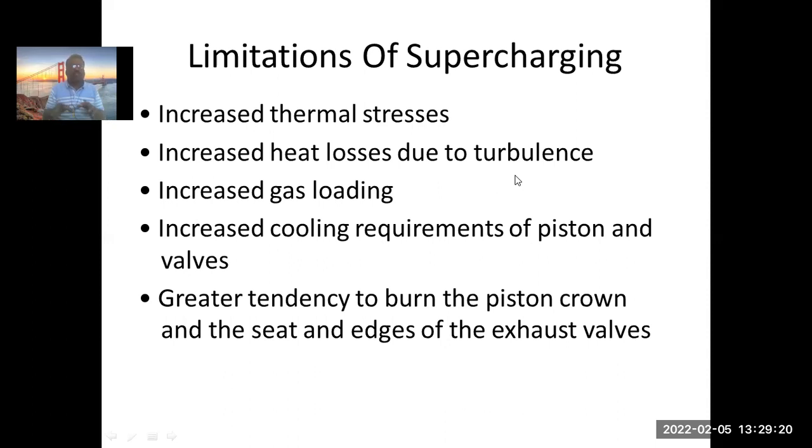So that process of bombarding on the walls is going to increase, and every time a molecule bombards, some amount of heat is transferred to the wall. And because the gases are at a higher temperature compared to the wall, correct? Since the number of molecules bombarding on the wall is more, more heat is getting transferred to the walls. In other words, heat loss is more, because what happens due to the bombarding of the molecules is heat loss. So we are getting increased heat loss.